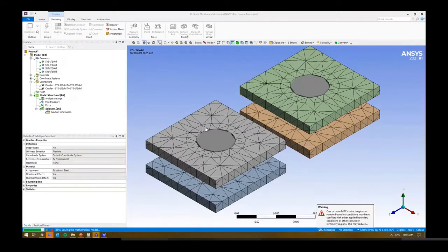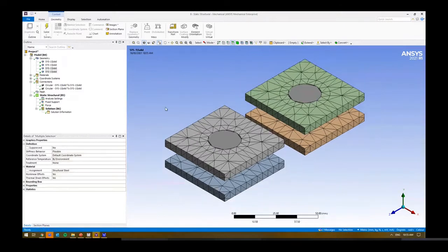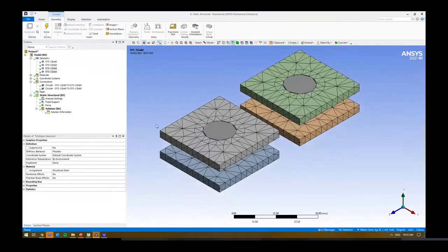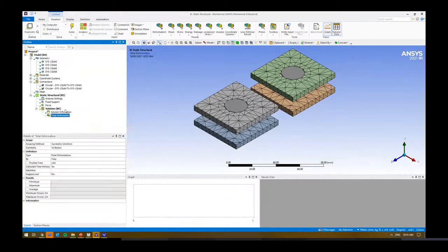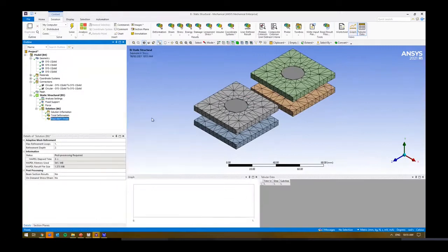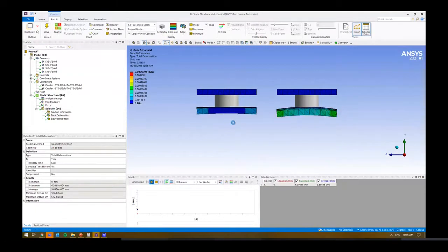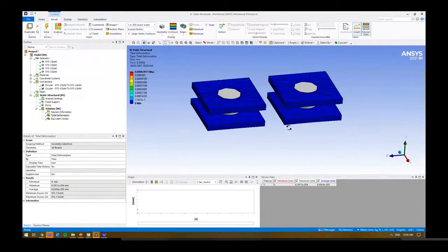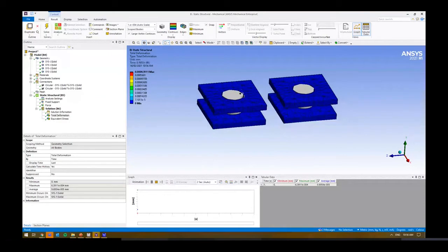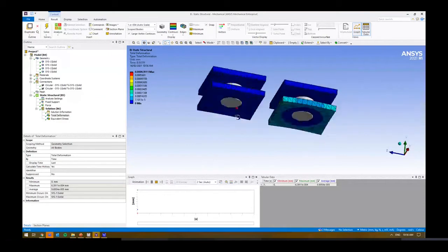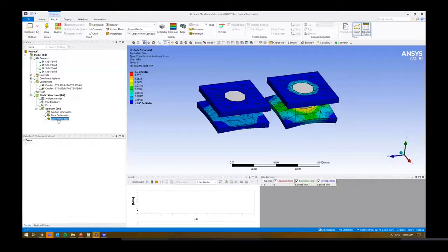What we're doing as well, by the way, is instead of explicitly modeling the bolt and the complexity of the geometry and adding all those features, we're just modeling the bolt as this beam element, and we've got load that's transferred through the beam element. So again, having a look at our deformations, if we extrude it out, we've got some similar deformations. Got a lot more over here. But notice we're fixing the face on the left to the face there, whereas we've got edge to edge.